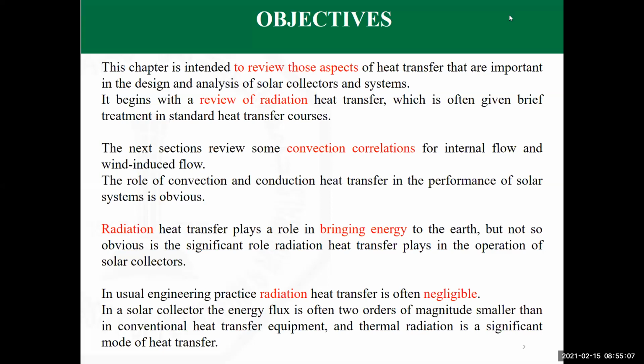Let me tell you, for example, that solar collectors gain heat by radiation from the sun, but heat is transferred to the fluids mainly by convection. So convection is one of the most important modes of heat transfer when it comes to industrial applications or even domestic ones. We'll be looking at internal flows, because solar collectors may have flow inside a pipe. So understanding the heating mode of the fluid here is important, and being able to estimate the heat transfer coefficient based on the conditions.